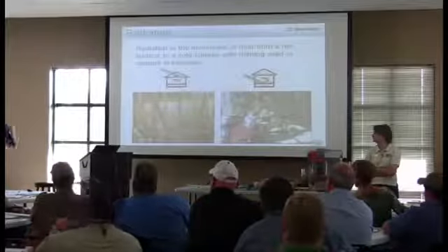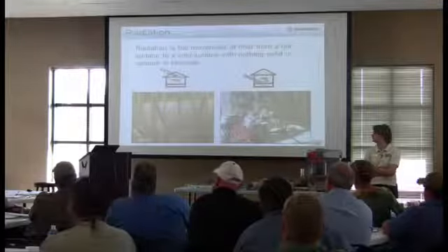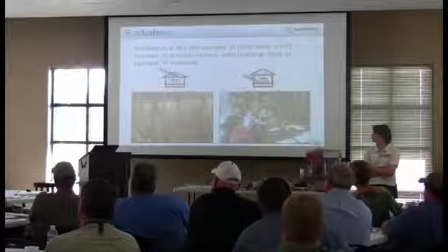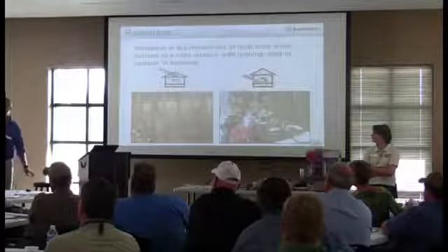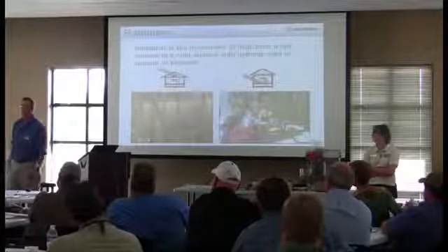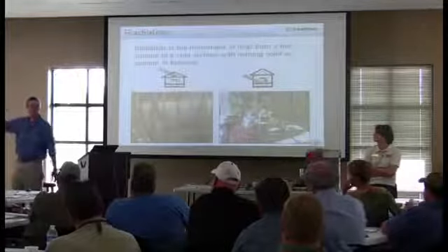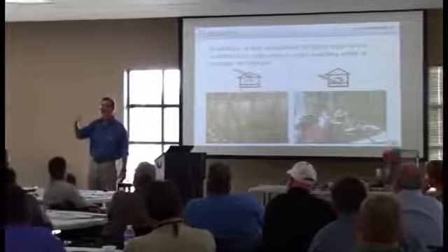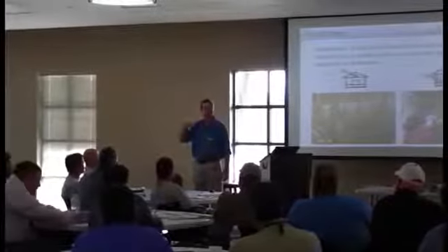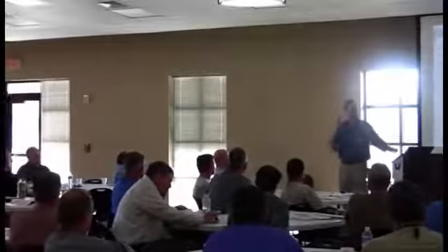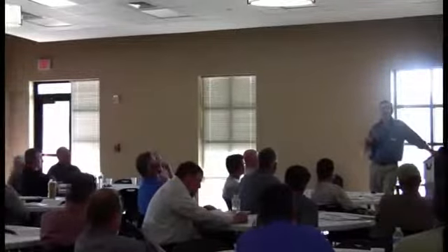So the sun, if you had, I don't know how big that is, I'm guessing maybe right here. That door and that side glass over there, that's probably at least 40 square feet, right? A door is about 20 square feet, so I'm going to say that's about 40 square feet. The sun is hitting that, believe it or not, with 10,000 BTUs per hour of energy. That is a lot. And here's the kicker. Let's say that whole thing is a single pane window.